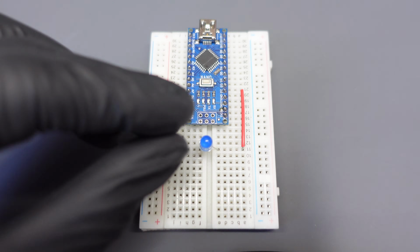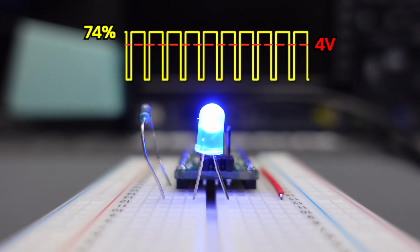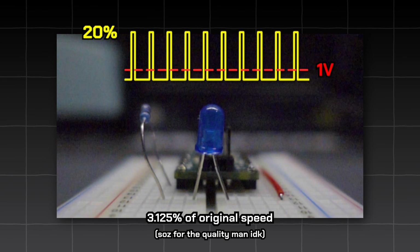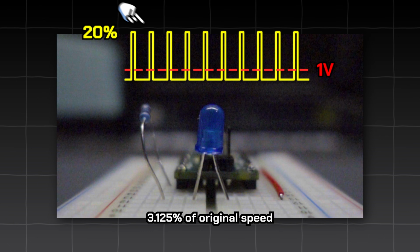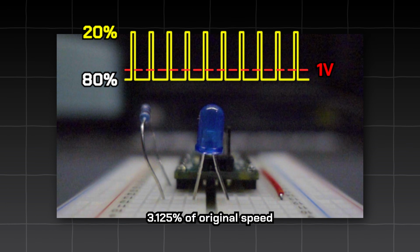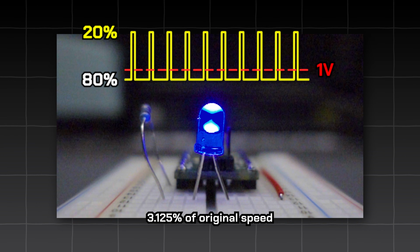Let's take this LED for example. Now I'm going to apply a PWM signal. It looks like it's getting dimmer and dimmer. Now it's at 20% power of what it was before. Now let's slow-mo this footage. As you can see, the LED is actually just turning on and off really fast. It's on 20% of the time and off 80% of the time. This same concept can be applied to the motor.